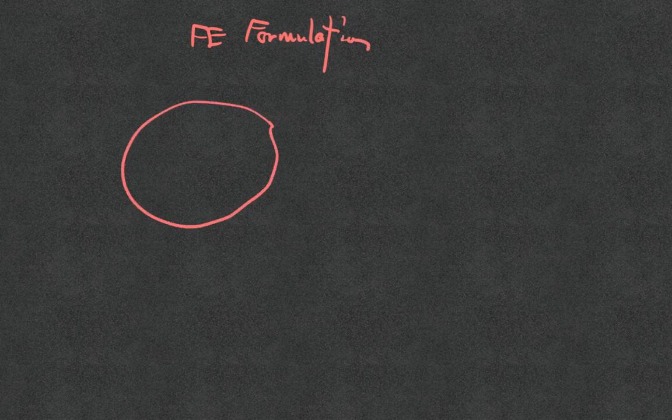Yeah, with that understanding, with that recap, let's write down the FE formulations. Okay, imagine there's a domain. The reason we don't want to solve it in an analytical way is that the world is not a square or circle. It has many different shapes. Okay, I will call this domain omega. Now I would apply the boundary conditions in some locations, and I will call this gamma s, which gives me the natural boundary conditions.